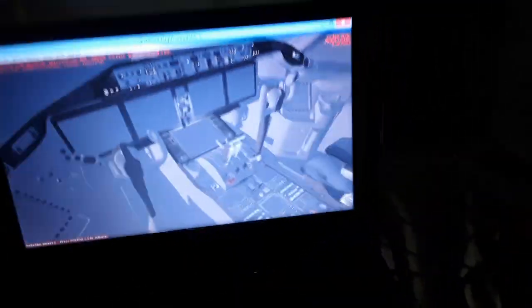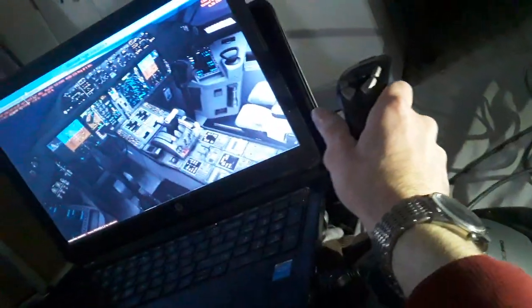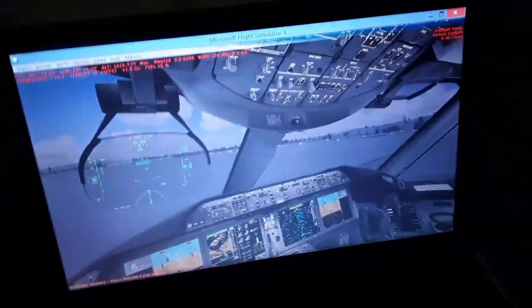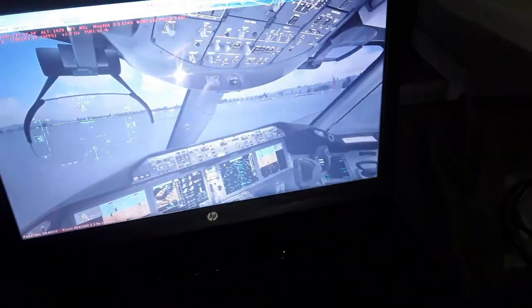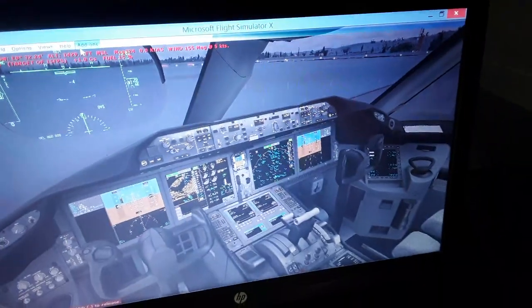We're going for the flight management computer. Over here, set up the flight management computer. We have not much time for this flight. So now I'm gonna set the flight management computer, enter all the data. It's gonna be used also from the autopilot flight director system panel when we fly the aircraft with the VNAV mode. So you can see I have the mouse pad here to control the keyboard, also the screen of the flight management computer.